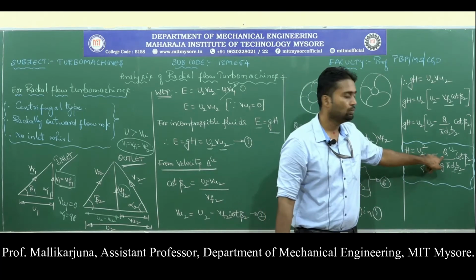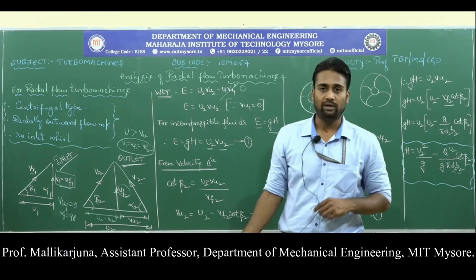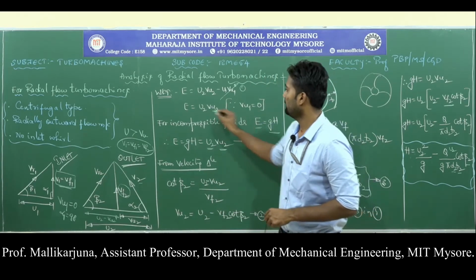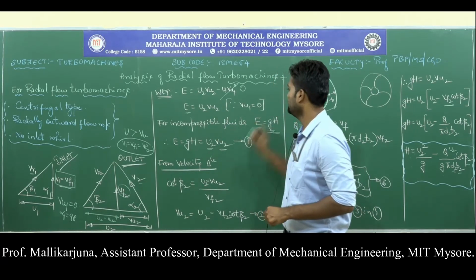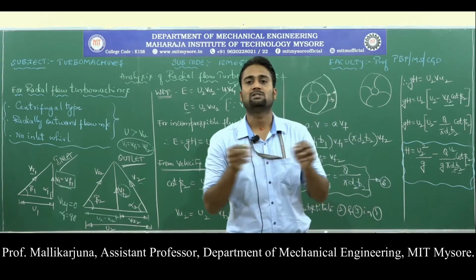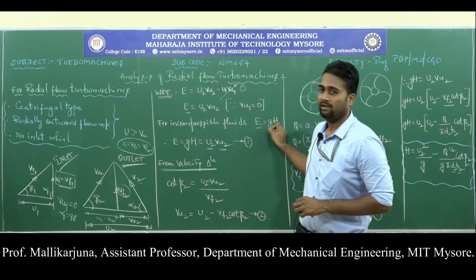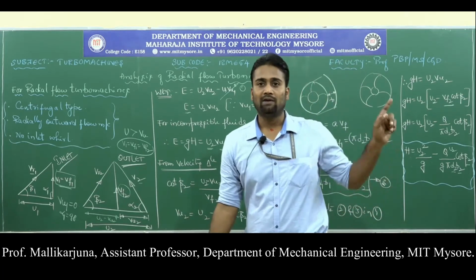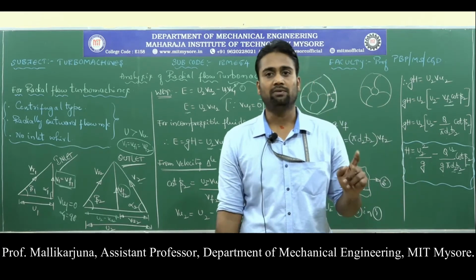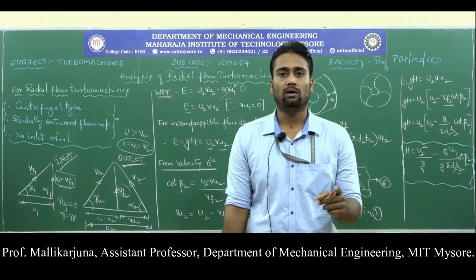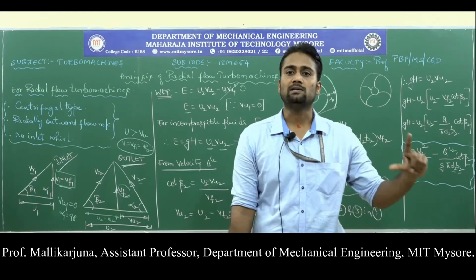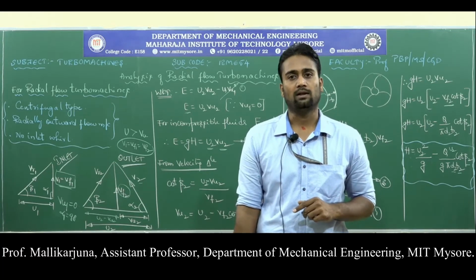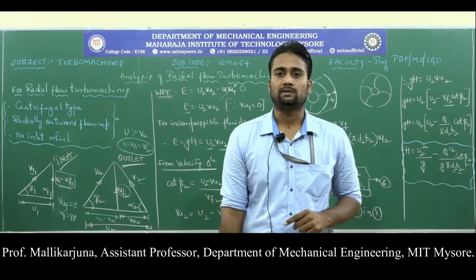So now H and Q are the new variables that we have introduced in this equation, because those two terms have come because of this. The energy transfer has been split in terms of g and H, and Vf has been expressed in terms of Q. Now we have a standard equation. With respect to that equation, we need to look on how the flow discharge Q as well as the head with which the machine is operating are dependent on one another based on blade angles of the turbo machine.